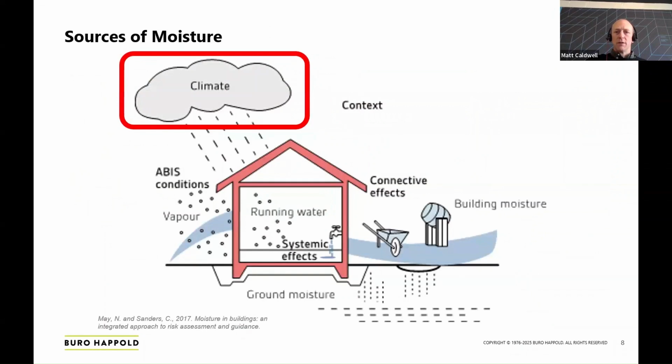So jumping to the issues themselves, there are a number of ways that timber might come into contact with moisture. During the construction stage, probably the most likely in most situations is precipitation. But there are other effects to think about: condensation, vapor, and then as the building starts to get fitted out, obviously you're putting in all your wet surfaces, which is another potential source of moisture.